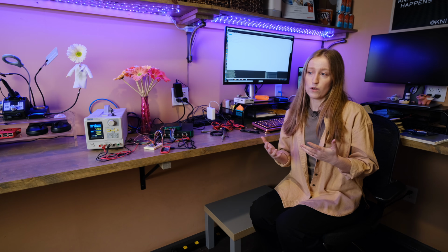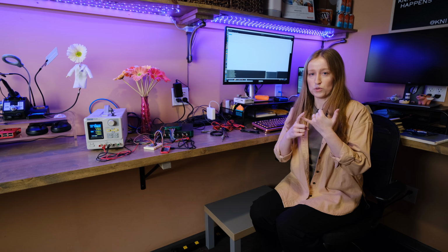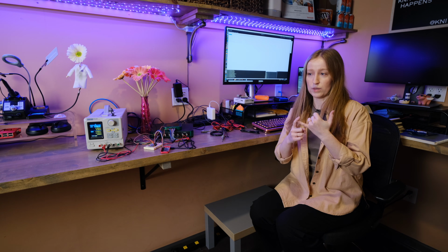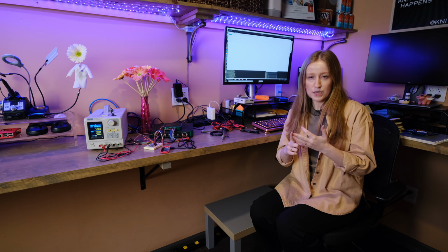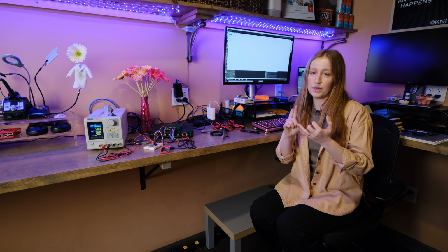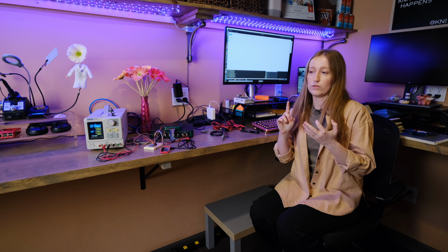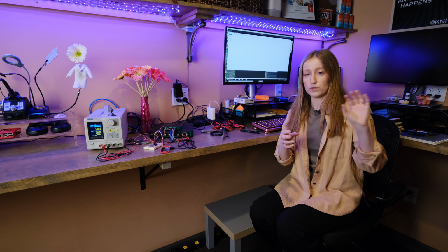And furthermore, that software has 3 main elements to it. It has the actual capability to create the programs for signal processing, providing signal stimulus. It has some sort of sequencer, so each individual test, like your power on versus your provide stimulus test versus your scope measurement test, each of those are compartmentalized, and then the sequencer runs each of those in the proper sequence. And then finally, a GUI element, so that it's easy to use, it's pretty, and it has a nice shiny on-off button.